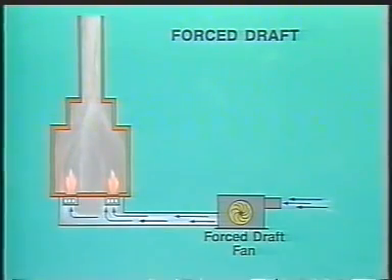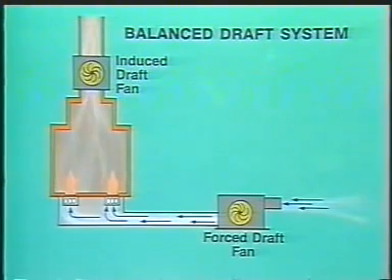Fired heaters, which use both forced and induced draft fans, are called balanced draft furnaces. In this system, a forced draft fan supplies air for combustion, while the induced draft fan pulls the flue gases from the firebox to maintain a negative pressure in the furnace.